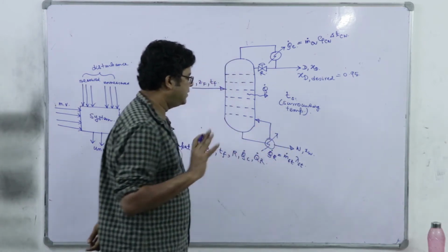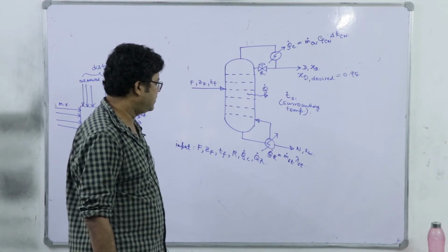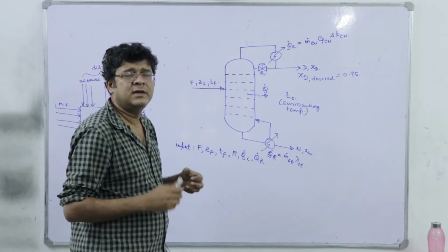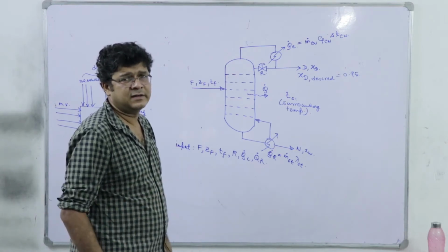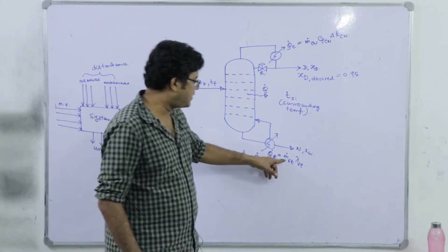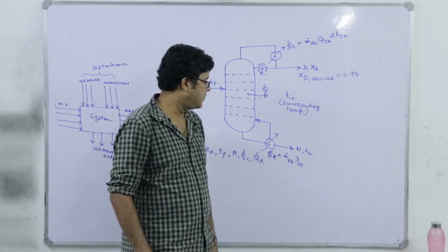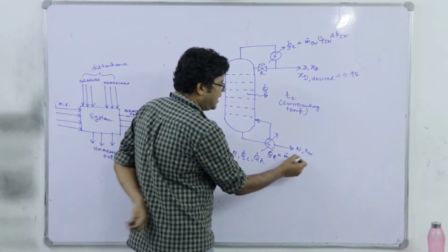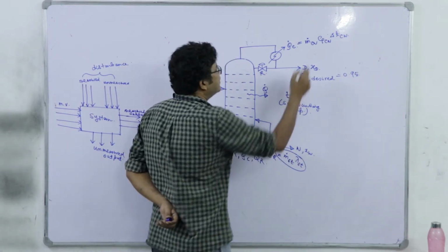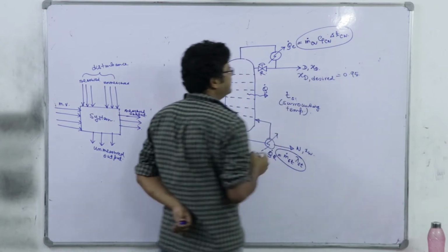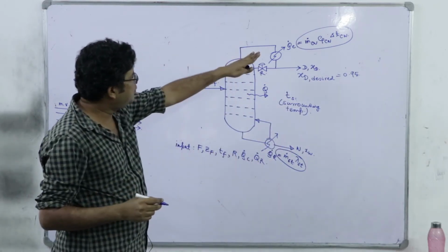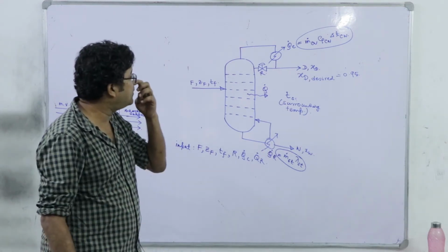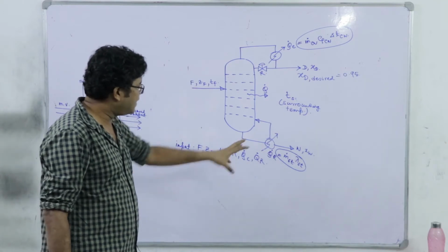We consider this latent heat exchange. For steam it is exactly true: the measured heat delivered by the steam is through condensation, and that is the respective latent heat. So if I change the mass flow rate of the steam, definitely Q dot R is going to change. We are not writing these equations explicitly, let us say it is implicit. So without specifying what Q dot C and Q dot R are in terms of m dot ST and m dot CW, let us keep it as Q dot C and Q dot R.